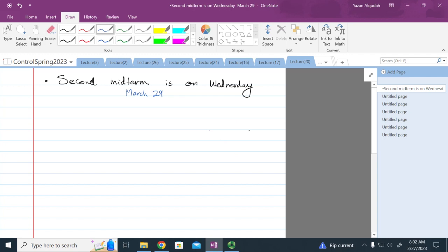But then we said, what happens if I have a root locus and we plotted it, and we thought using the gain alone is going to enable us to control the system and give us the behavior we want? But after we plotted the root locus, we realized changing the gain alone is not enough. I want my system to have poles at these two locations. And if I change the gain alone from the root locus, there is no way I'm going to be operating at this point.